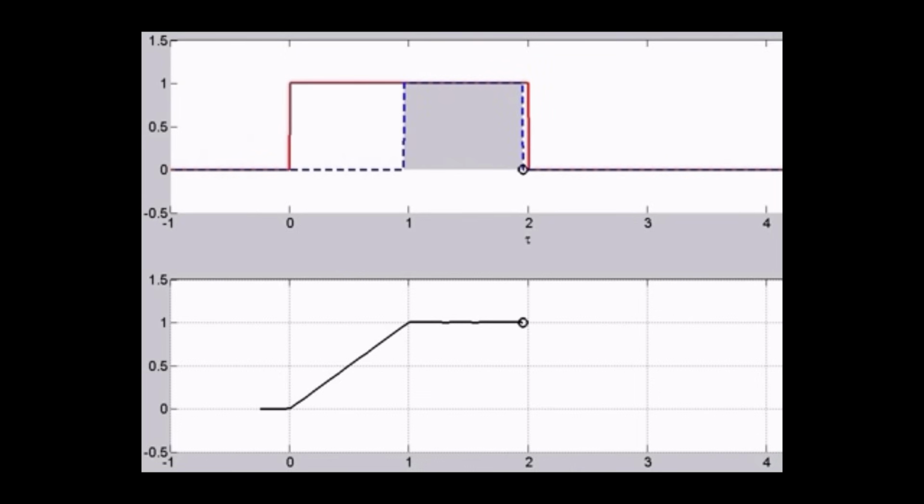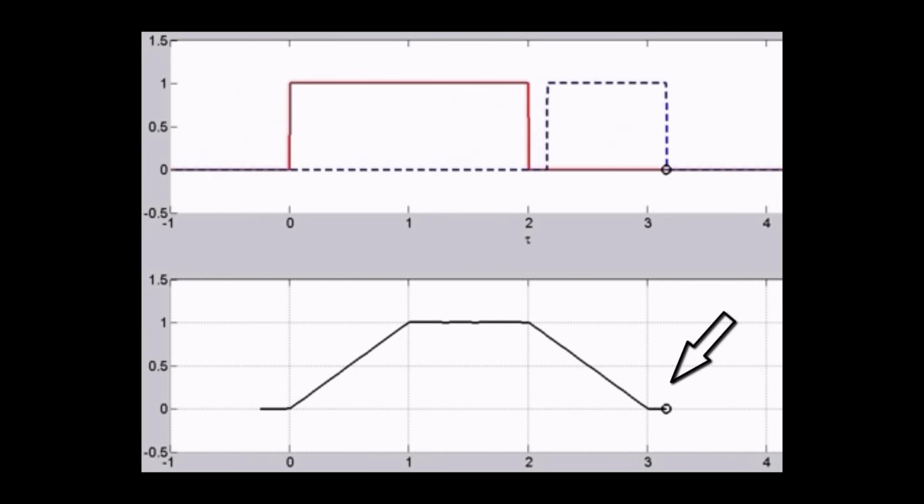And you can see that in the second window. Here you can see the convolution is initially equal to 0, and then it is increasing linearly, and after some time it becomes constant, and when the signal ht minus tau is moving further, the amount of overlap is decreasing and the convolution is also decreasing and finally becomes 0. So I hope this animation is clear to you.